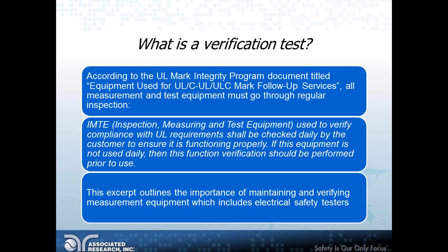According to the UL Mark Integrity Program document titled Equipment Used for UL-C-UL/ULC Mark Follow-up Services, all measurement and test equipment must go through regular inspection. The IMTE, inspection, measuring and test equipment used to verify compliance with the UL requirements shall be checked daily by the customer to ensure it is functioning properly. If this equipment is not used daily, then this function verification should be performed prior to use.